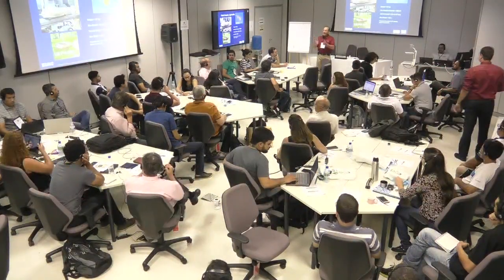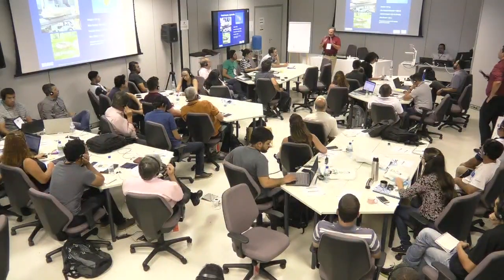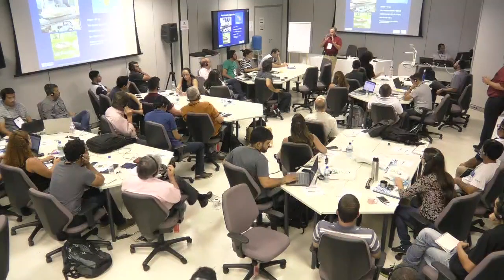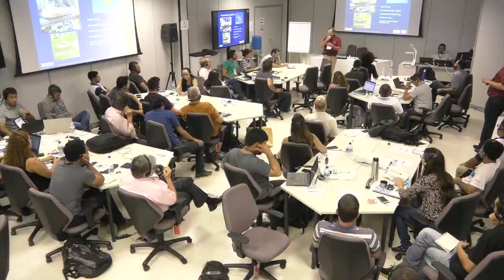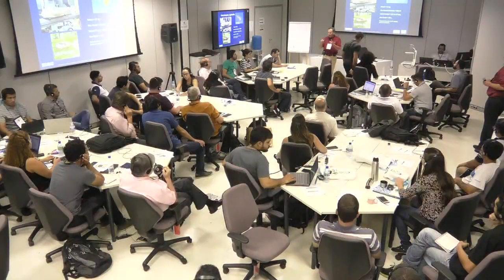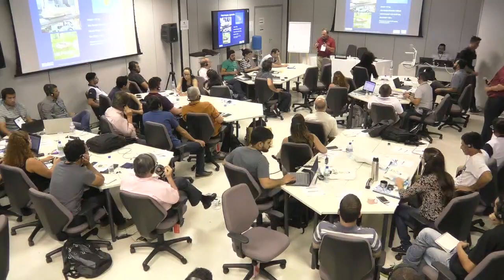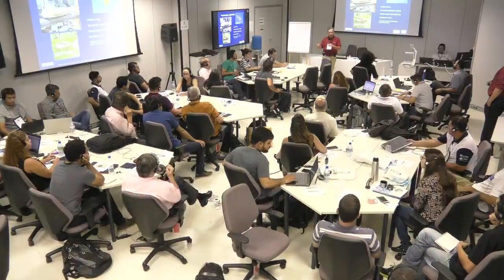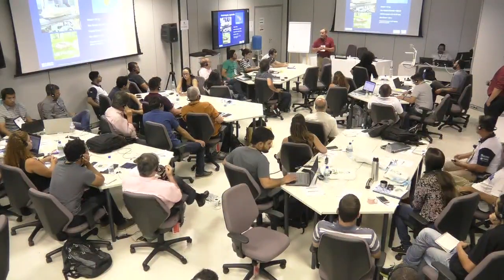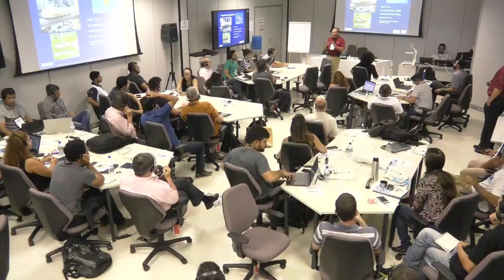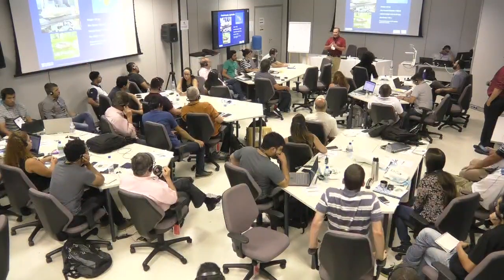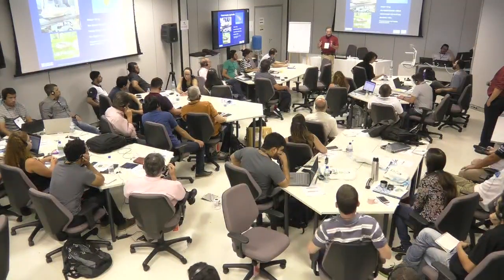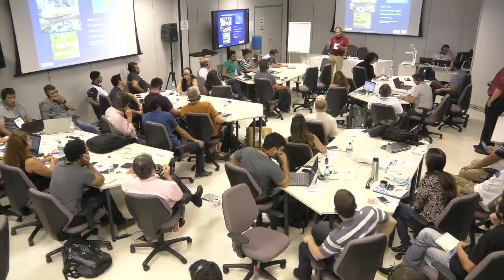So we use the live readings. And we try to get that mean velocity there. It does change, but I think that's true. That's actually what's going on. But we have compared it to both, and if our boat is static and everything is working the way it should, and our sampler and our nozzles are good, they're not like the ones that I passed around, that have a nick on them, and we're all set. We end up with good, I mean, it's 100, 101%. We can have 90% efficiencies. We're good to go.